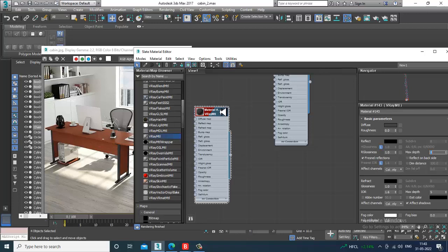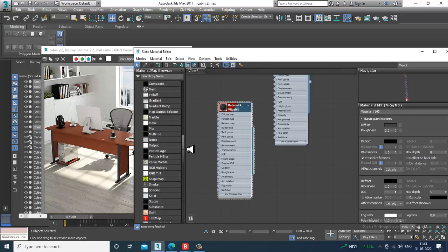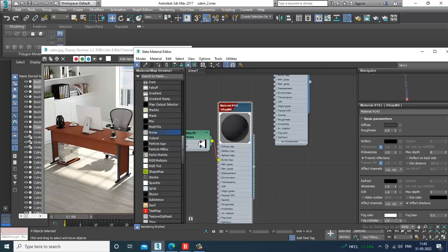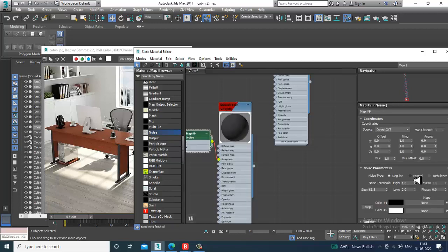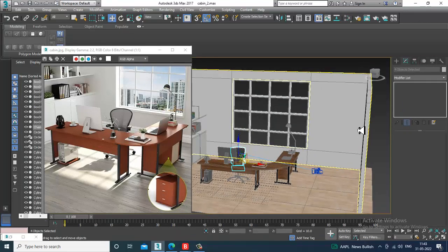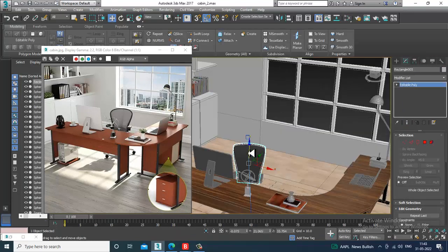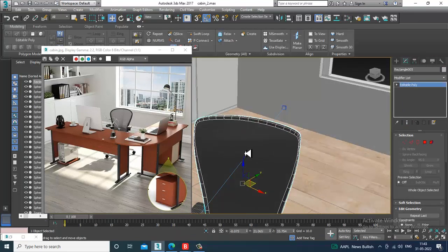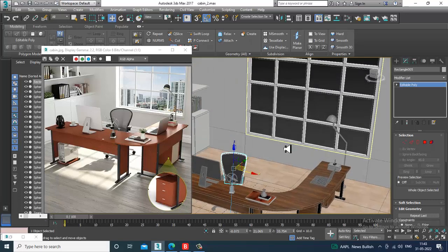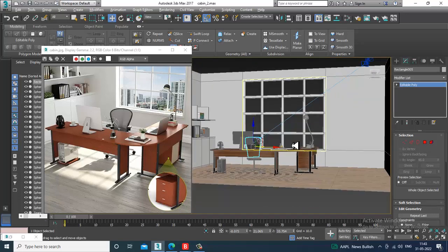after that, I can add a bit of noise over here. So let's just add noise to the bump map. So go into the bump map, make it as fractal 0.02. Let's give a bit of noise to it. If you want to give this as lattice over here, you can give that, but you need to add some segments if you want to give lattice over here. That can also be done. That's not a problem.